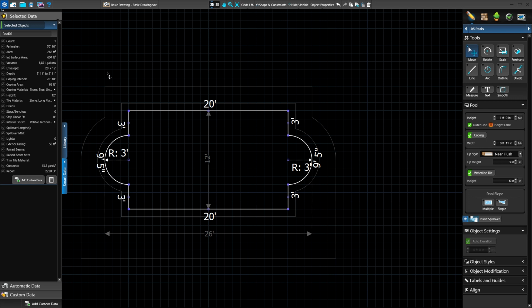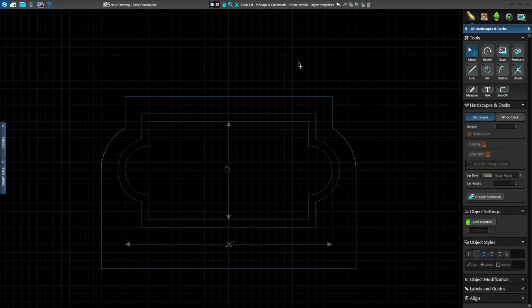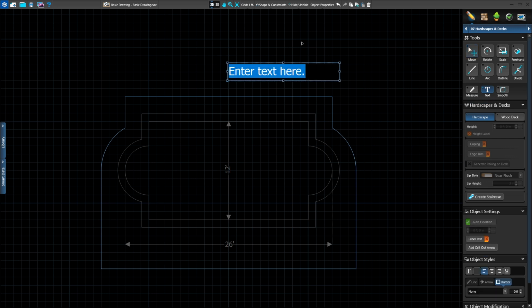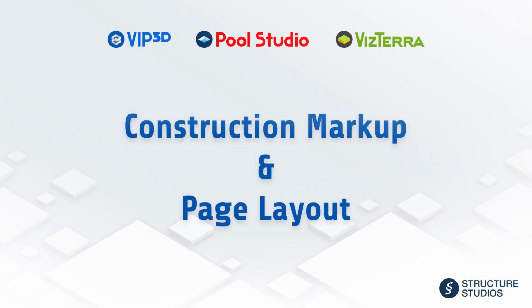Back in the Smart Data menu, we can use values such as envelope to see similar measurements calculated automatically for us. The next guide, the text guide, allows you to label objects in your design and add information. Simply click on Text, left-click to create a text block, and use the keyboard to enter your text. The guides are primarily used in the construction phase. For more detailed information on all the guides, please see the set of construction videos.